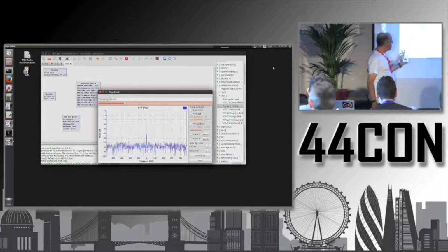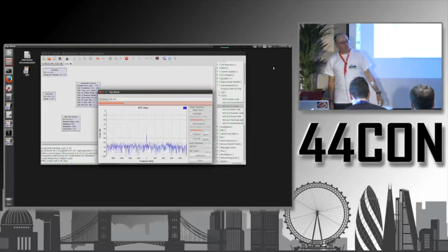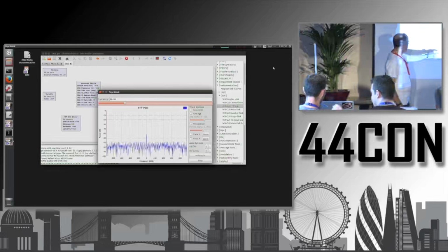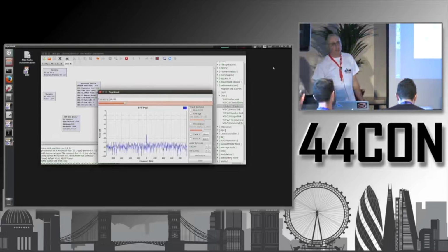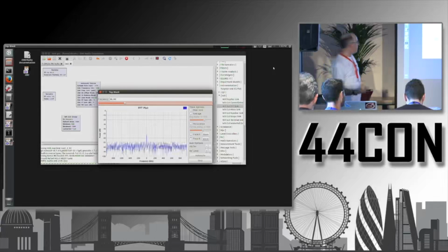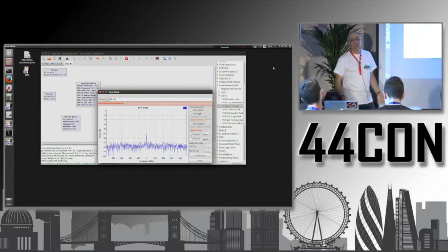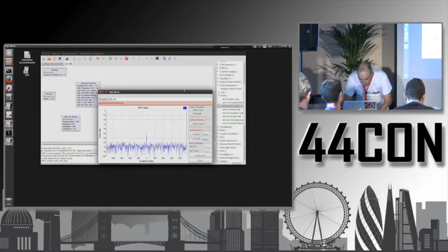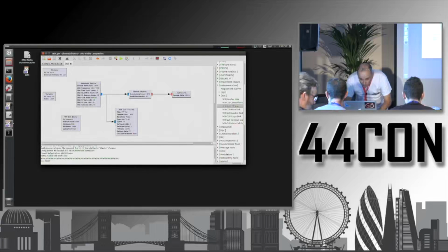So that is something that I also had in my room at 186.4 megahertz. I have a carrier wave here, unmodulated. If you select that one, first of all you can see the peak here. But also if you play the audio, it's much less noisy than the surrounding, and that's because it's unmodulated. So when you demodulate it to audio, it's like there is no sound, just silence. Can stop this.